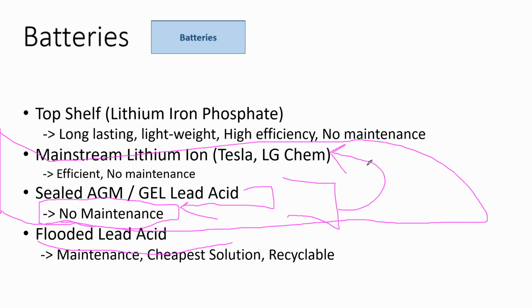If you have a client who is more hands-on and you have a site where you can do a larger battery that emits gas, which can be vented to the outside, such as a house versus a condo, then you want to consider flooded lead acid.